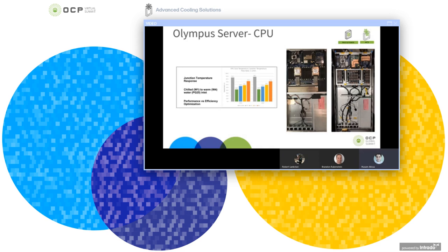The uber point here is that the use of liquid cooling enables us to make decisions such as run with colder water temperatures, potential to take a hit on efficiency, but an enabler for further chip performance. So there's a trade-off to be made here. Another option would be to run warmer water, enable infrastructure efficiency gains such as dry coolers, etc., and still potentially run colder than a case of air-cooled solution.